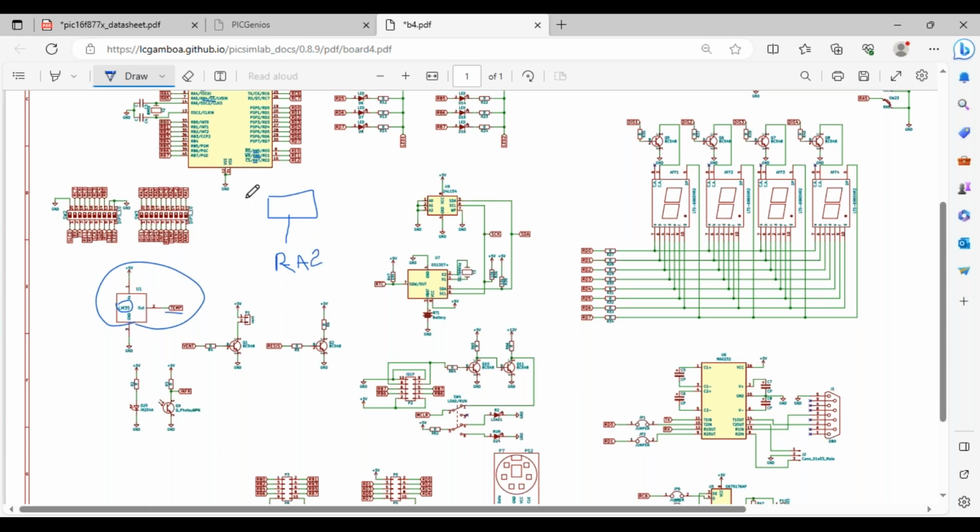First of all, you have to do a comparison to turn on the buzzer. For example, you take a temperature sensor and convert its value into a digital value. If that digital value is greater than some predefined threshold value, you provide 1 to this particular pin of the microcontroller, which will turn on the buzzer.